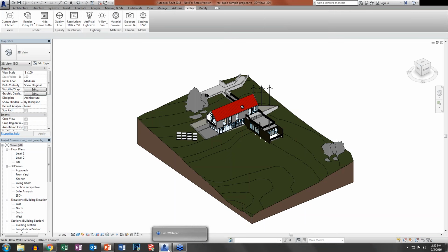Cool. And is there any way to assign a generic IES light for the non-physical lights globally? That's exactly what happens out of the box globally. So what happens is if it doesn't find your specific IES, so if you haven't loaded an IES to your light fixture in the Revit database or in the Revit light fixture, Revit family, it will automatically assign the generic IES to that and use that in its stead. So it will use Revit's defined generic IES profile.